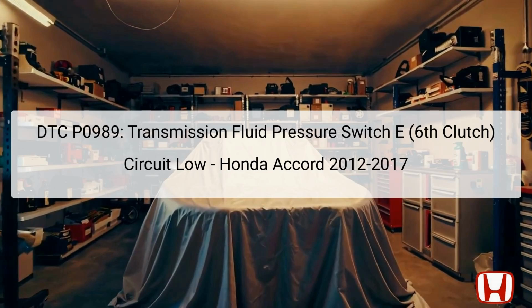The diagnostic trouble code P0989 indicates an issue with the transmission fluid pressure switch E for the 6th clutch in the Honda Accord models from 2012 to 2017. This error arises when the electrical circuit associated with the transmission fluid pressure switch shows a low signal, preventing the vehicle from shifting into gears other than 3rd or 6th due to the fail-safe function.